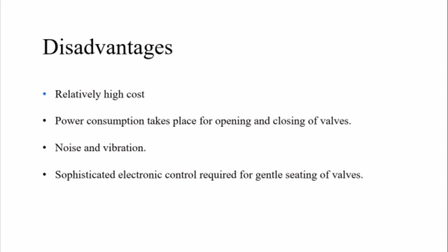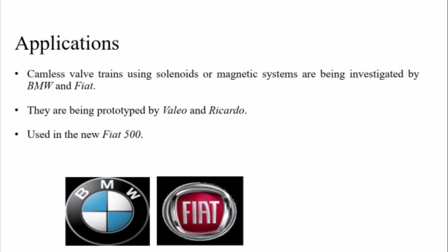Coming to the disadvantages, the first disadvantage is the relatively high cost. That is, the camless engine costs more. The second disadvantage is that it takes power for opening and closing of the valves. That is, power consumption takes place for opening and closing of the valves. There is noise and vibration present. The next disadvantage is that we need more sophisticated electronic control units for gentle settling of the valves. These are some of the disadvantages which we can see in the camless engines.